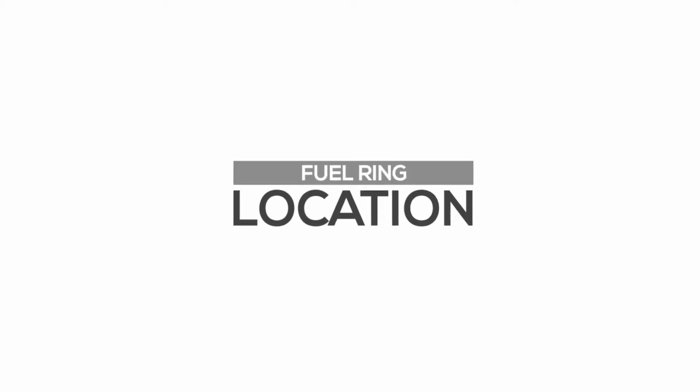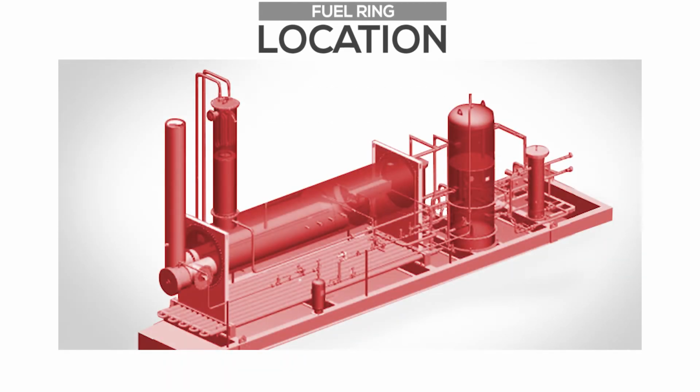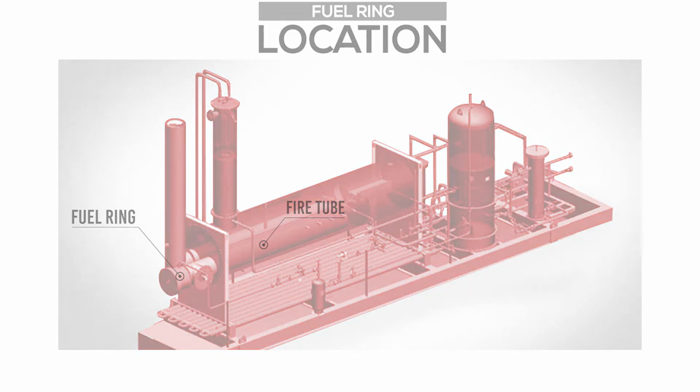First question: where is a fuel ring located on the process equipment? A fuel ring is usually located on a glycol regen skid. It's installed on the back side of the natural draft burner inside the fire tube of the glycol regen skid.